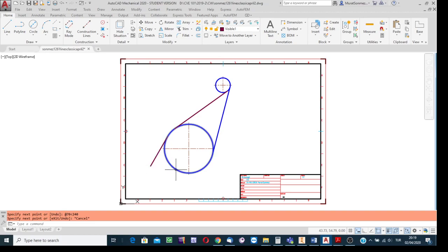First, change the snap setting after starting the line creation process, and then indicate the circle. The second trick, don't forget to have the at symbol. Third trick, after writing the length value into the box, to teach the software that the other box is for the inclination angle, click on the angle key of the keyboard. And the last trick, write the inclination angle as measured in the counterclockwise direction relative to a horizontal line which passes through the tangent point of the line.